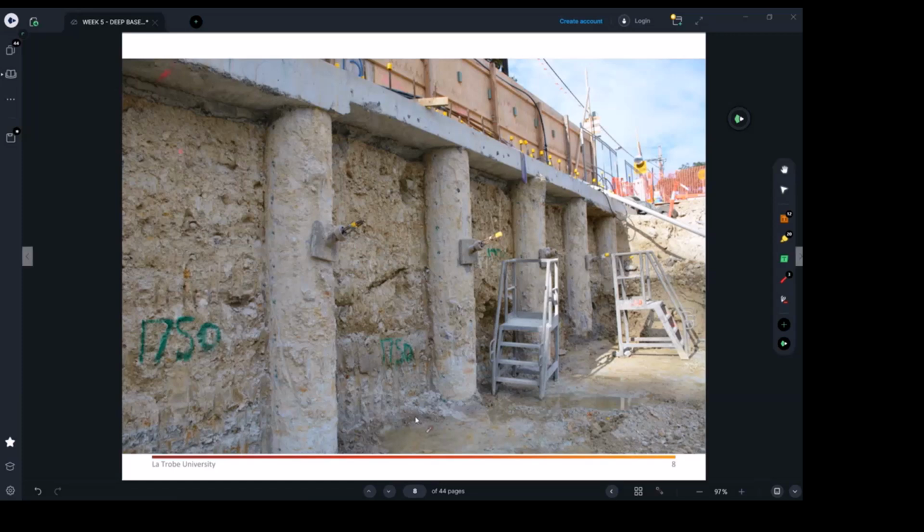What we do here, we just embed the bottom of the pile by 1 meter below the basement level, and we use anchors close to the top. So that's a different consideration and a different technique if required. And again, if the situation allows, because sometimes this anchor will usually go probably 10 meters into the soil.